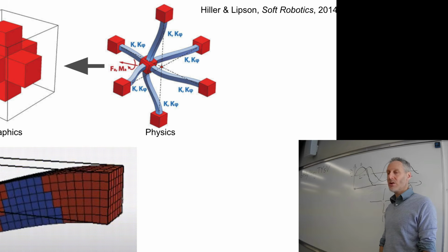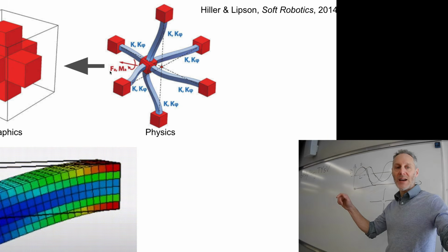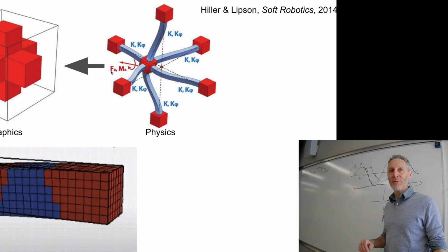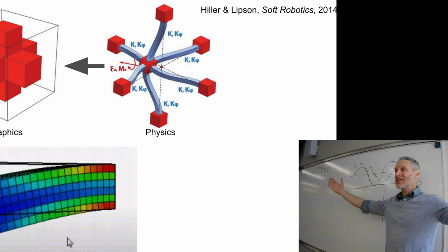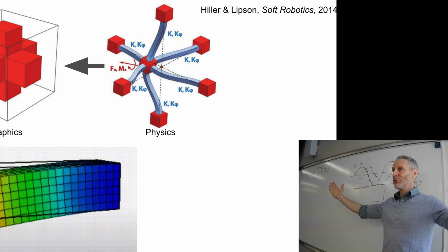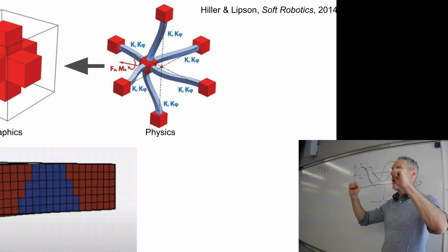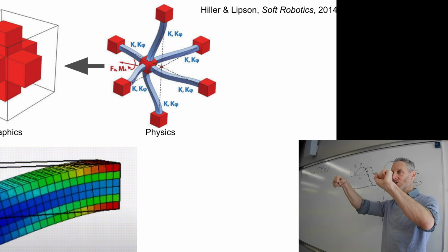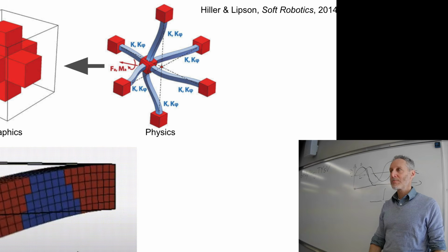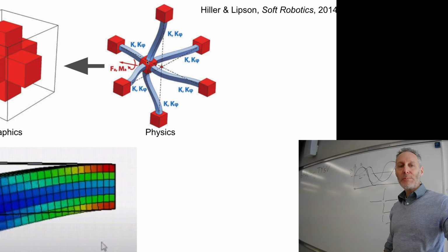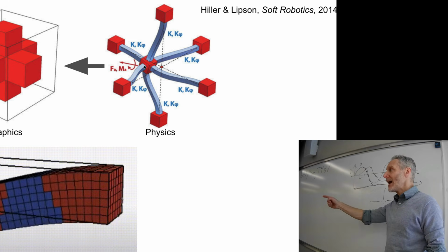Okay, so we just talked about stiffness, which is how much the material resists forces, F sub A. We'll just ignore the A for our purposes today. So F is a vector with 6 numbers in it. How much horizontal force is being applied to the object, how much vertical force is being applied, how much force in this direction, how much torsional force or rotational force in this direction, and the other 2, which I can never remember. Yeah? Okay, so at every place where the beams come together, VoxCAD, like PyBullet, sums up all the forces that are acting there.